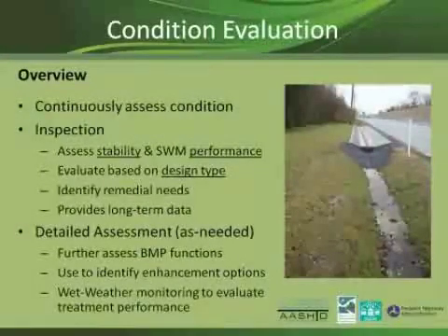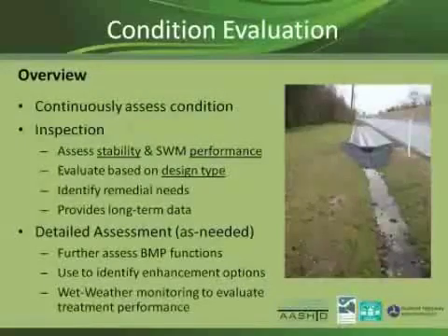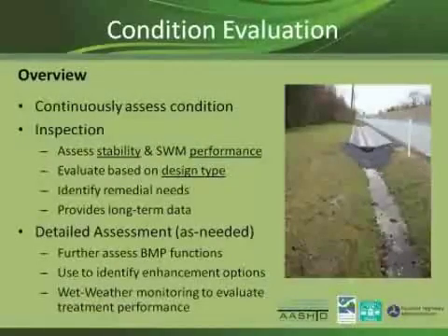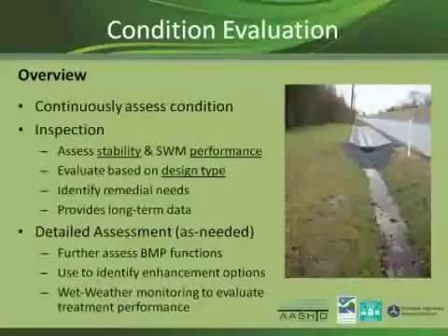That being said, let's get into the condition evaluation. The overview is basically you're trying to assess your condition, and it's a combination of not only its stability as it's standing, but also its stormwater performance. And as I stressed earlier on, you can only evaluate based on the type of design. A pond definitely functions very differently than an infiltration device versus a filtering device.